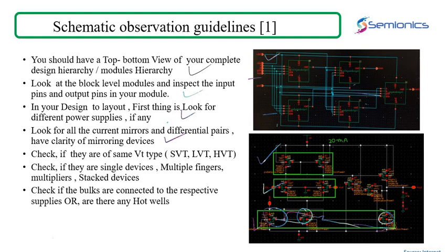Now you also need to be very sure, when you're doing the matching, that you zoom in. Sometimes when you look at the circuit, it looks like, oh yeah, all these are current mirrors, differential pair. You will just start doing the floor plan of that and get going. But it's very much advisable that you zoom in properly and have a look at whether it's a single device, whether it's a multiple device, whether there are multiple fingers, or whether it's a stacked device. Sometimes we tend to make some mistakes.